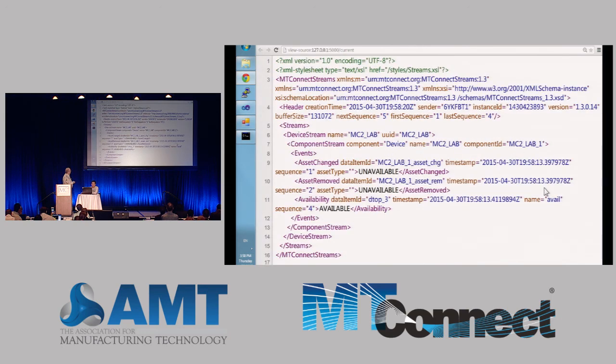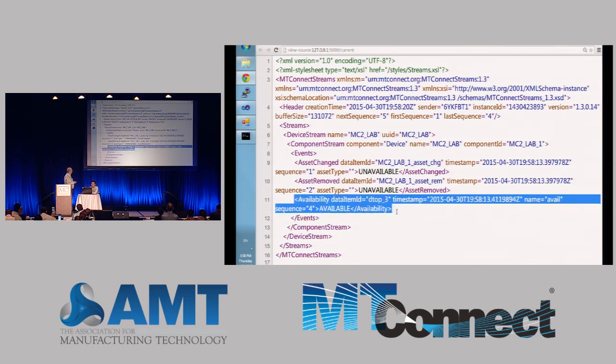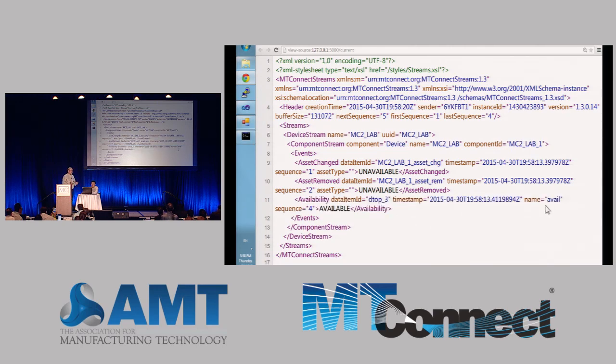Now I wanted to actually show you quickly the actual XML here. What's really important here is when you're naming your data items in the adapter, this name is what the agent is going to be looking for to take the values for that data item and plug it into the XML data stream. So it's very important to remember, whatever I name that in my adapter, I have to have the matching name when I set up my XML.